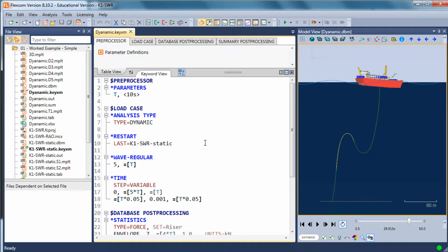So when you're doing riser design or analysis work, you won't just consider one single regular wave. In reality, you have lots and lots of different regular waves of different periods and different incident wave directions. You may even have different wave amplitudes. You may also adopt a random sea approach where you might look at different combinations of Hs and Tz or Tp in a wave scatter diagram. So in summary, you can have hundreds and hundreds of different dynamic simulations. So here I'm going to show you how you actually go about creating those.